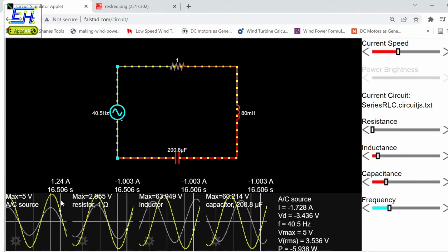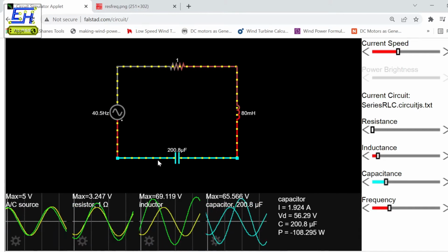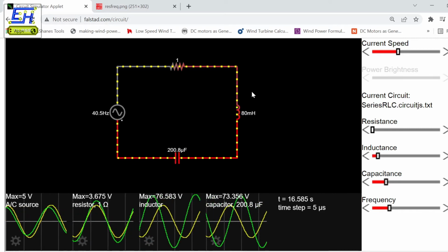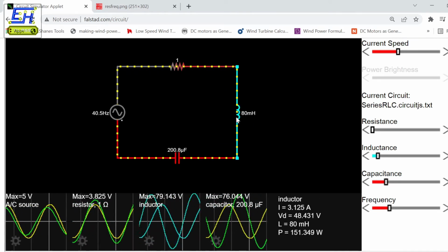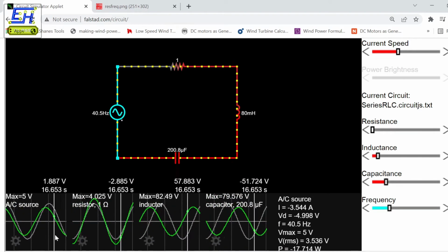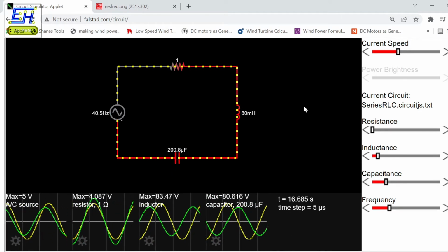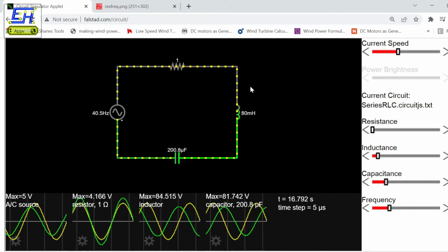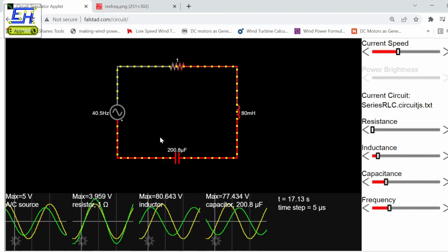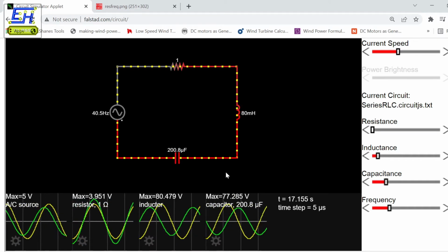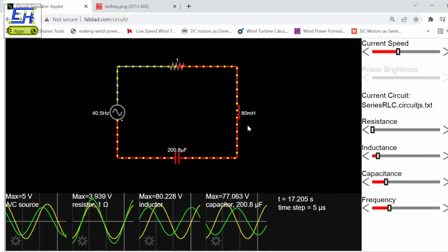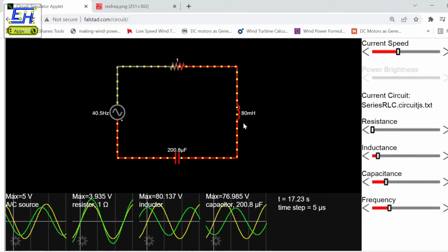How is this possible? Even if you have these two elements in series in the circuit, and we already know that the capacitor and inductor shift these waveforms, why then do we get a perfect match? The explanation is very simple. In this condition, the effect produced by the inductor is nullified by the effect produced by the capacitor. And what are these effects? They are their individual reactances.